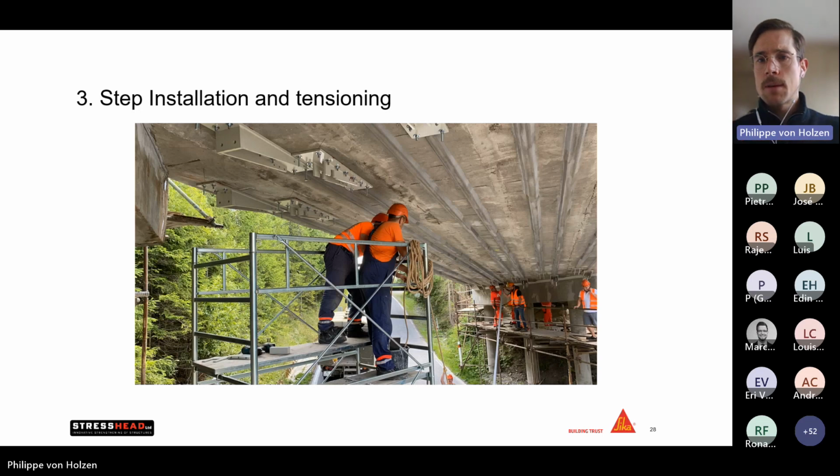Now, as soon as the epoxy is applied on the whole length of the tendon, we can start with the installation and tensioning process. Here is the view on the fixed anchor side. As you can see, the whole installation can be made under working conditions, which was required, and the installation can be made by hand. Now we have my colleague Marcel, who is as well today in this call, and here on the other side is me. We really go to the job site and help and train the contractor to install the system.